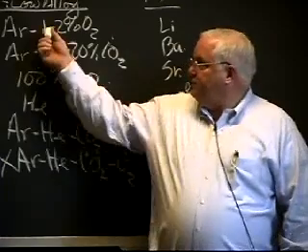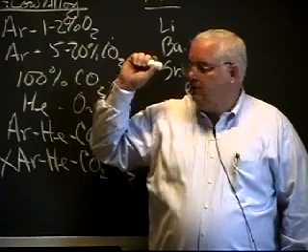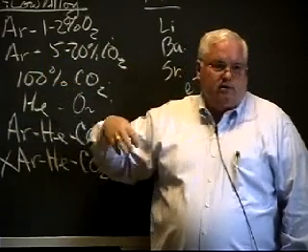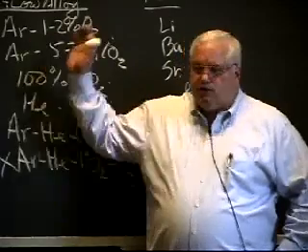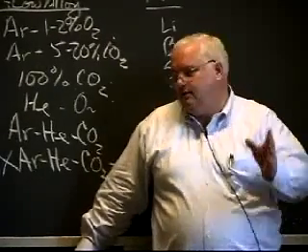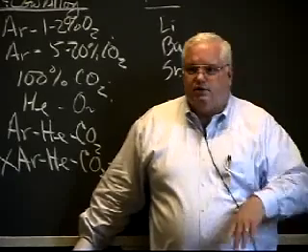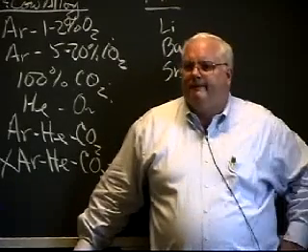And certain types of steels might have a little bit of titanium or niobium in them for a beneficial effect. If you try to weld it with this, you won't get any recovery of that alloying element in the metal. So there's lots of weld metal chemistry. This is why we train welding engineers, to study all the nuances of this. It could be a whole course if you wanted to.